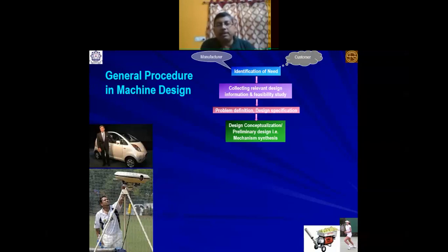Your most important mechanism is the spring, by which you give the energy, momentum or force to the ball. If the spring fails by fatigue after 400 balls and you have to replace it, then it is not techno-economically viable.